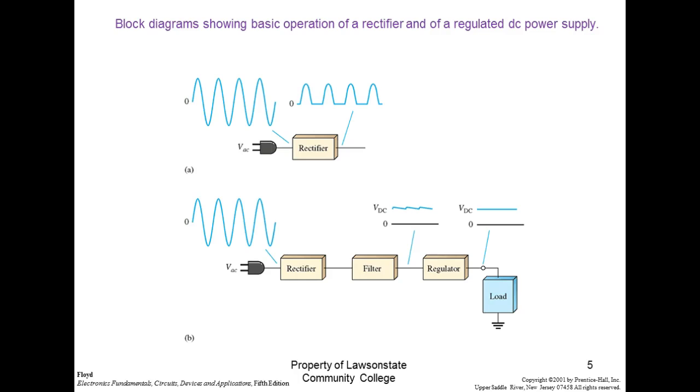Efficiency would be what you get when you measure the power on the input and the output, so the efficiency would be power out over power in, right? You understand? Then we'd multiply that by 100, and that would give us our efficiency. And what we would find out is the output power is always going to be less than the input power, and that's true, right? Energy produced is always less than energy consumed. So input energy is always more than output energy, unfortunately.